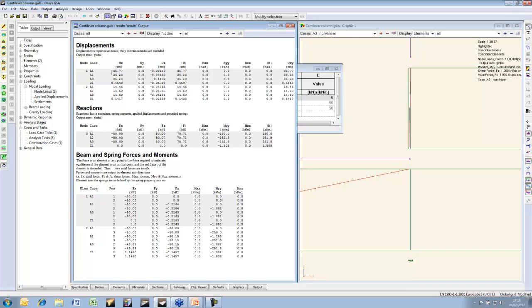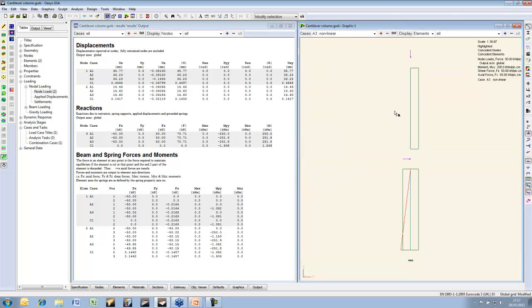Okay, allowable deflection of 33 mil is on the limits, really linear there, but you notice that the linear, the P delta and the non-linear analysis have basically given the same deflections, and if you see down here the axial loads and bending moments and so on are essentially the same, with very little difference between the three analyses.